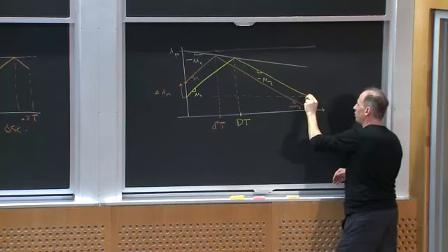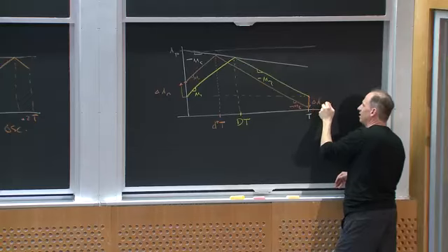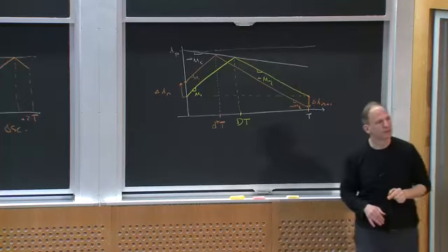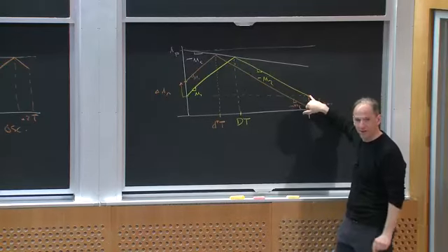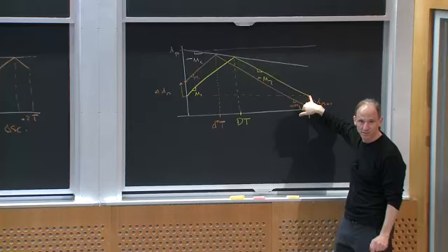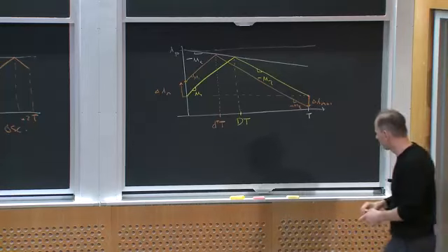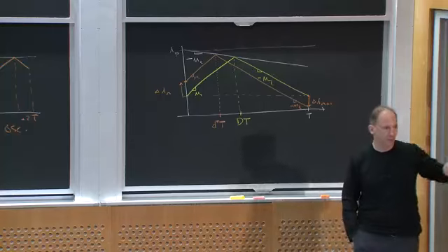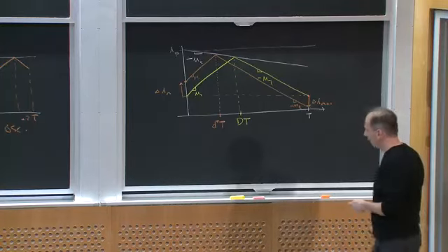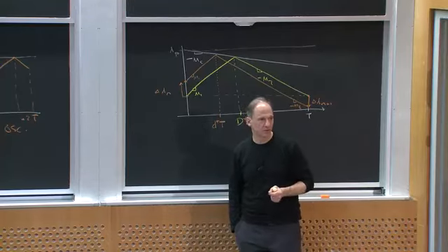And then he would end up with some error at the end of the cycle, or the beginning of the next cycle, that I'll call delta I n plus 1. So if he starts off here, he's going to end off here, and I have a different error from periodic steady state at the beginning of the next cycle. Does that make sense? So let's see if we can quantify what that looks like. Again, this was done by the Middlebrook group, and it's in a paper that we've posted on Canvas for you. This behavior is also described in a book chapter that we've also posted on Canvas.